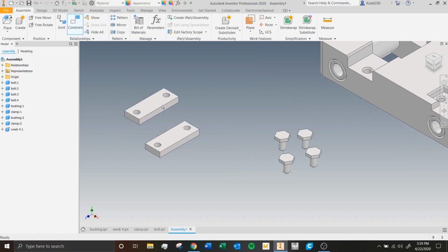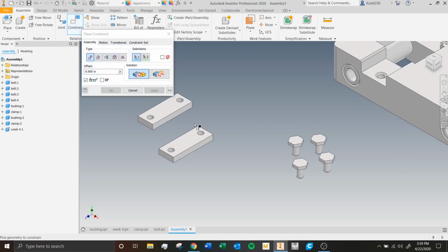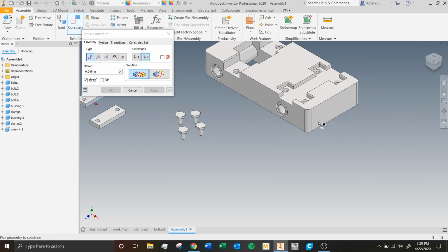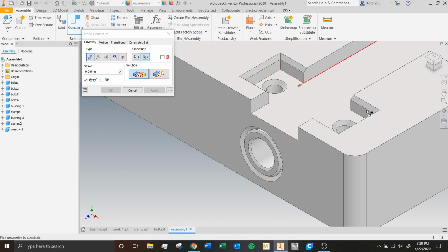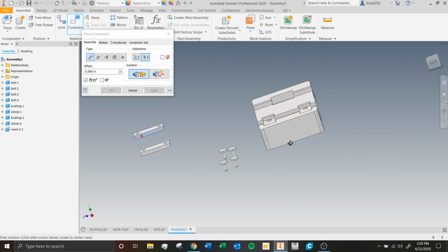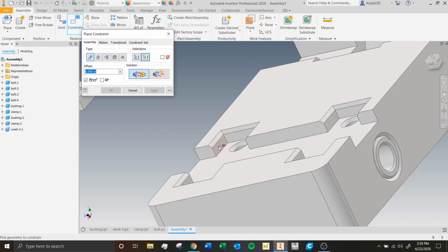And now we have these little clamp tabs. So we're just going to go ahead and use the surface one. We're just going to select surfaces here. Now the nice thing about holes is that when you mate them together, it makes it really easy to put everything together. But in this case, I'll show you how to mate something like this if we didn't have these holes. So for these tabs, we're just going to select one of the faces, go on this portion right here, and here these slots. Now you'll notice I selected this face, and the long way it would go over here.